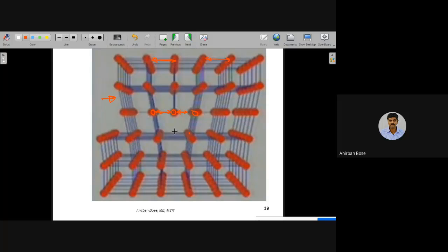On the other hand, if you see just below that region, you will find that they will be under tension, because the distance between them is quite larger with respect to the regular atomic distance. Okay, so this is what is meant by compression and tension in comparison to the perfect part of the crystal. Clear? Yes, sir. Okay, so this is the defect, and you have understood this is the line around which this defect occurred, and this is called the edge dislocation.